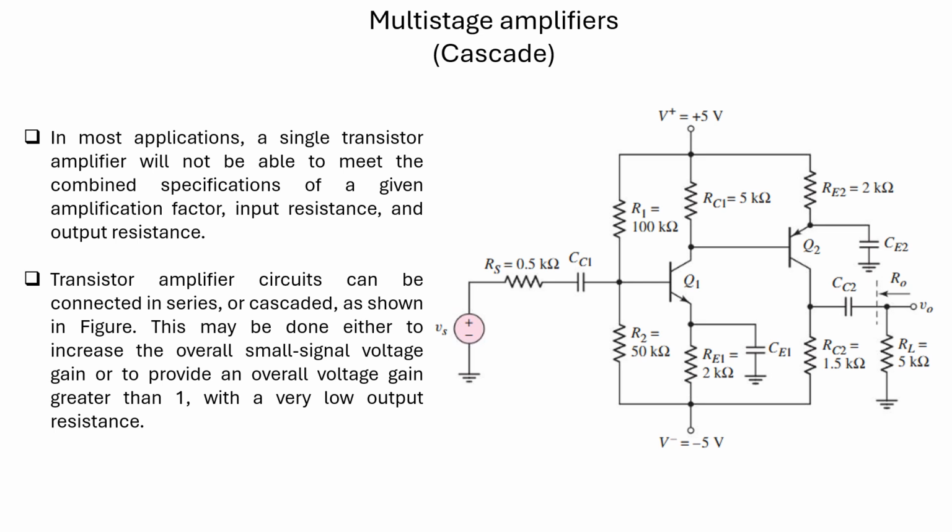The same output passes to the base terminal of the Q2 transistor, meaning the output of Q1 acts as the input for the second stage. Finally the output is collected at the collector terminal of Q2. That is why we achieve a higher amplified version of the input signal.